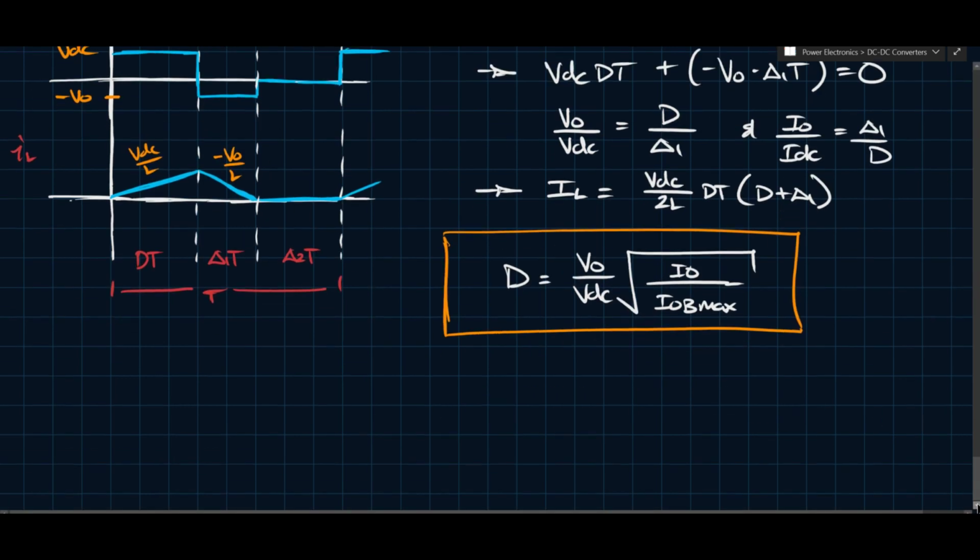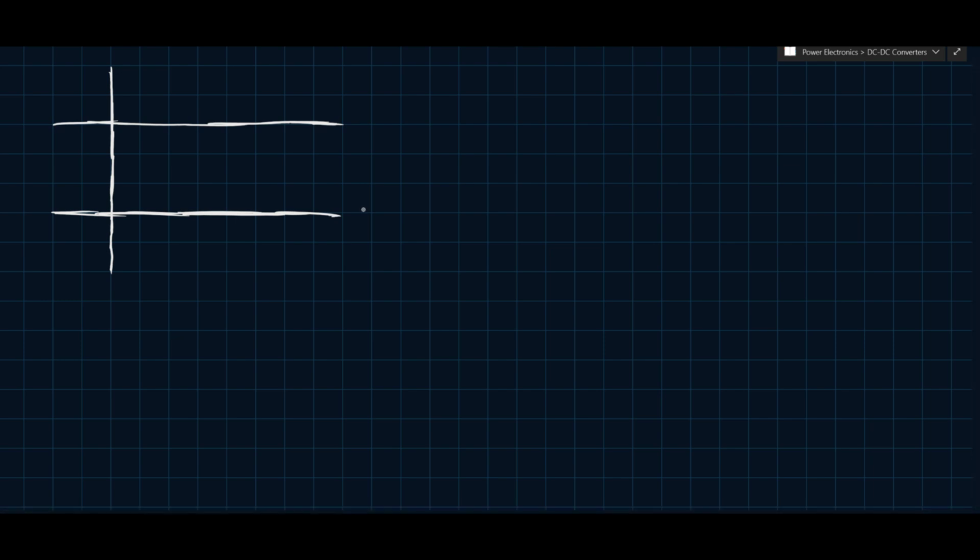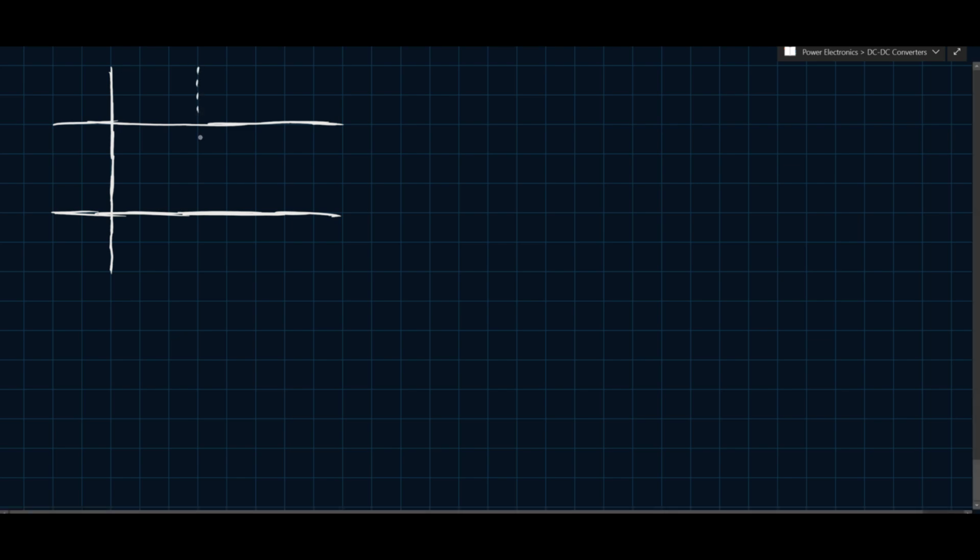So the last thing we want to look at here is the voltage ripple on the capacitor. To do that, we're going to take a slightly different approach than the one we've used in the previous videos. This one looks at the charging and discharging of the capacitor: because you can integrate the current waveform, you can determine the net charge during that time. You basically want the net charge in the capacitor to be 0, and we're going to establish that type of relationship here for this converter.